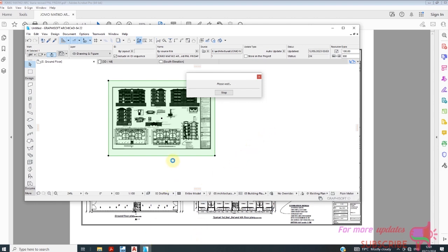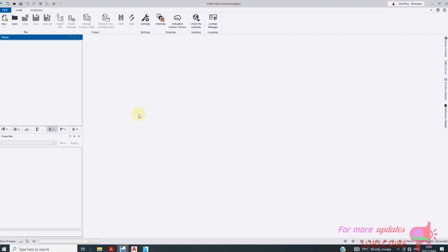So I'm not doing my general arrangement in AutoCAD because to model this building, you need to determine the grids and the spacing between all the grids that you will need. If you do not model correctly in Tekla Structural Designer, you'll get validation errors.